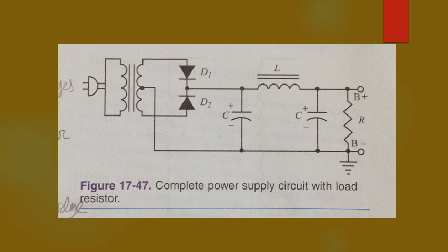Second, the load resistor improves regulation. The load resistor acts as a preload on the power supply. It causes a voltage drop when the equipment is attached to the supply. The added drop is fairly small and the regulation is improved. That is also a reason why the power supply draws energy constantly when connected.